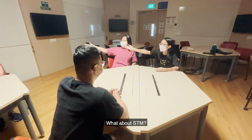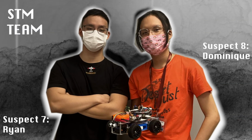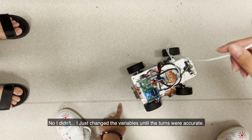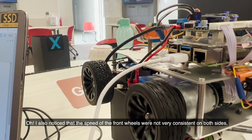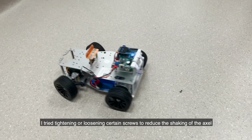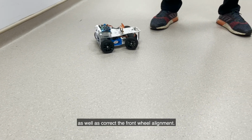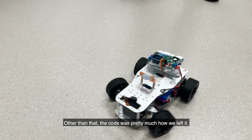What about STM? Did you do anything without me? No, I didn't. I just changed the variables until the turns were accurate. Oh, I also noticed that the speed of the front wheels was not very consistent on both sides. That must have been why our robot couldn't move straight. I tried tightening or loosening certain screws to reduce the shaking of the axle as well as correct the front wheel alignment. Other than that, the code was pretty much how we left it.